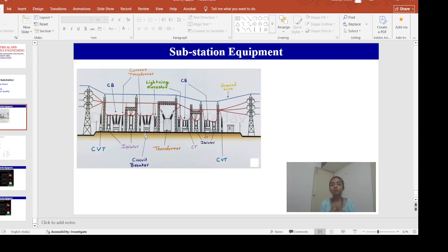In that case, the fault is detected by the circuit breaker, and it feels the necessity to release the potential energy stored in it. In order to release the potential energy, it needs to separate the two contacts. During this process, some conductive plasma or ionized plasma is generated, which is called an arc. As a result, the circuit breaker will try to extinguish or quench that arc.